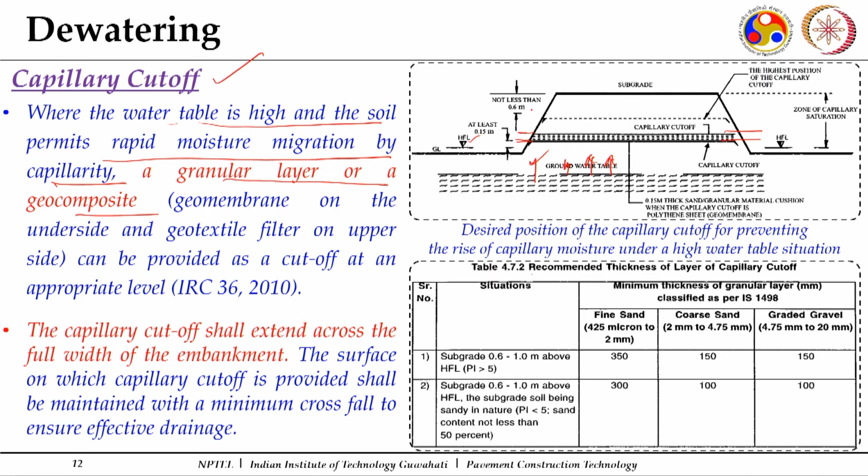It is mentioned that between the bottom of subgrade and the capillary cutoff, a distance of at least 0.6 meter should be there.